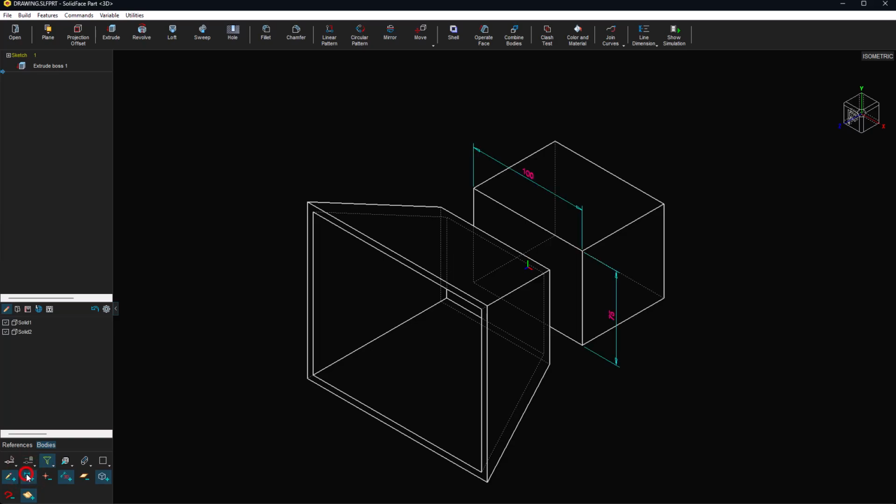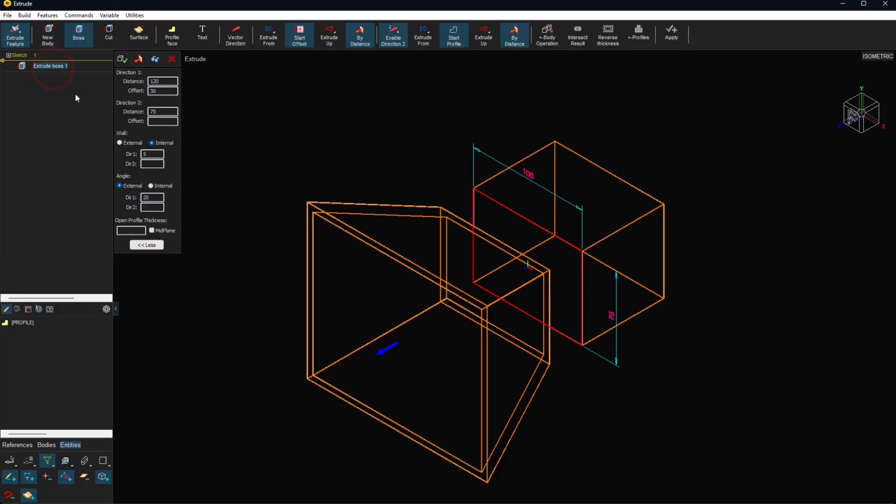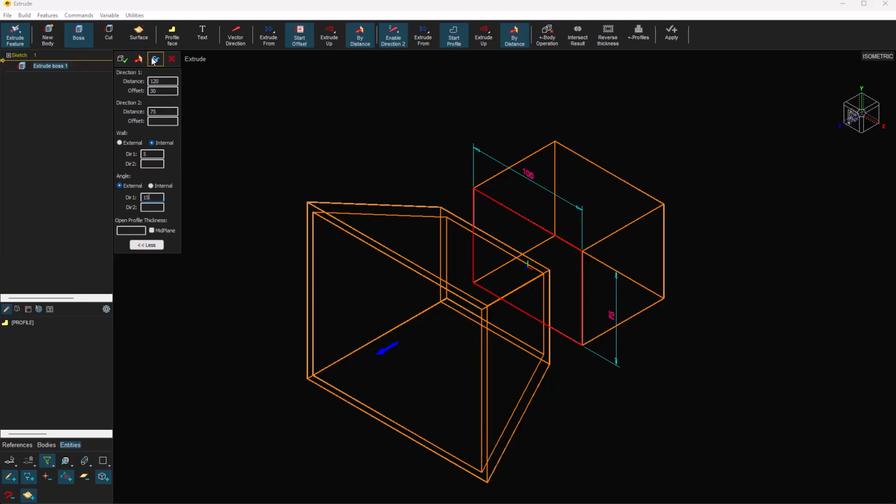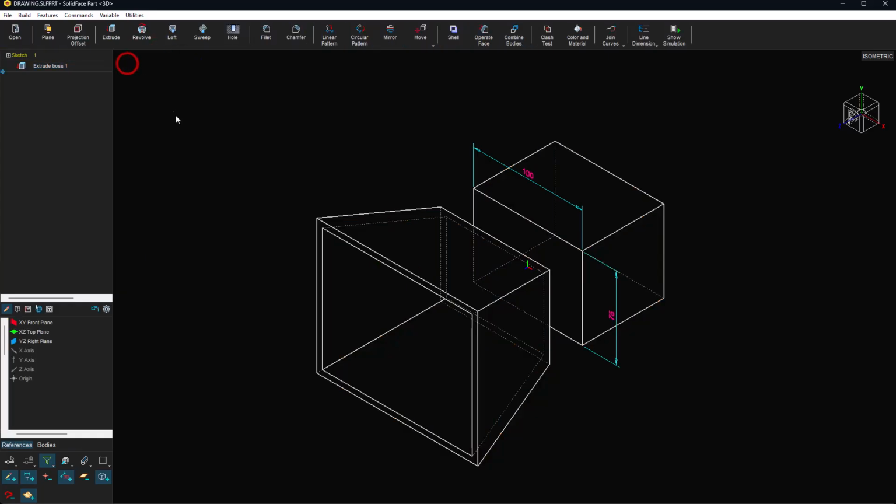To edit the sketch or feature, click twice on the feature and its position in the list, or on one of its faces in the graphic screen. To edit the distance, click on the arrow and with the right mouse button pressed, drag the distance. In the dialog box, edit the angle to 15, creating some 3D dimensions of the model's edges.